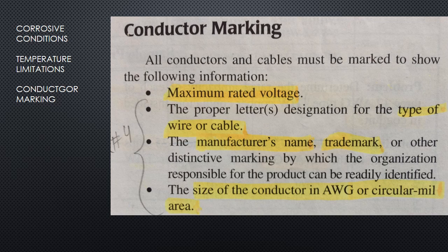If there are many conductors close together, they will all release heat, raising the temperature of the surrounding air, reducing the amount of heat they can release. Insulation greatly reduces the heat flow between the conductor and the surrounding air.